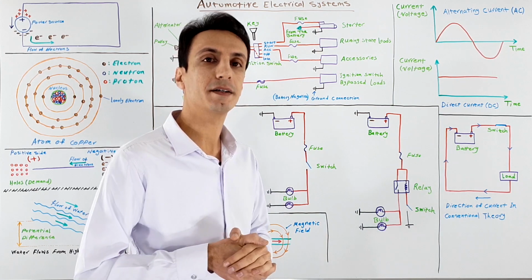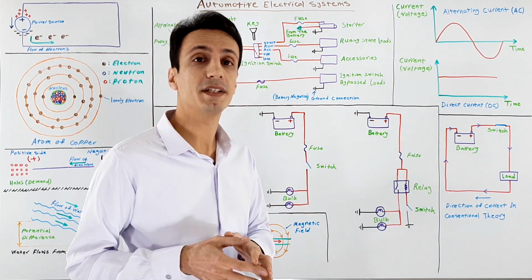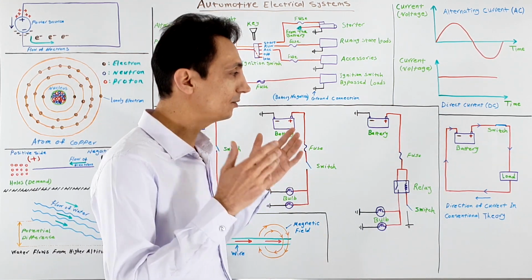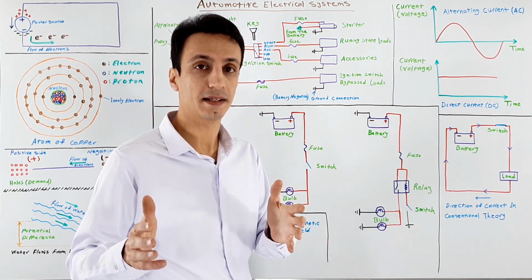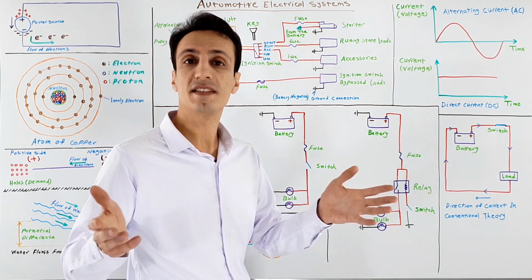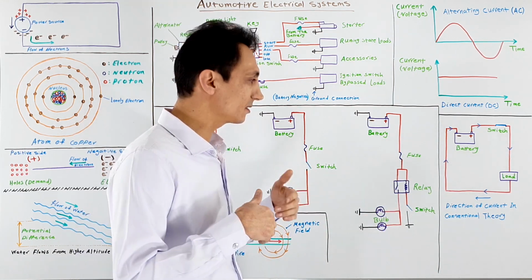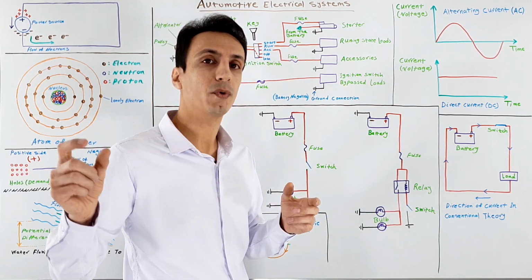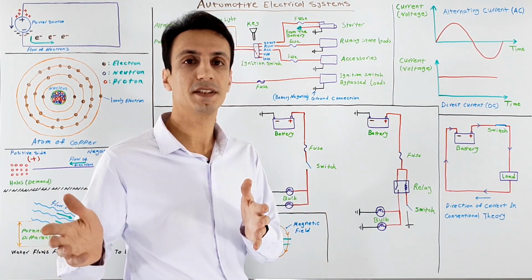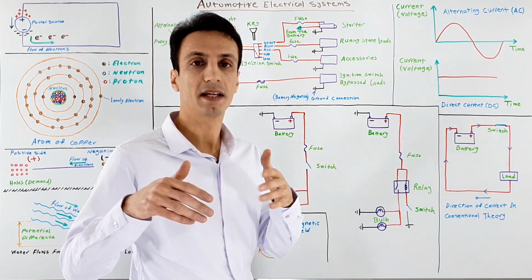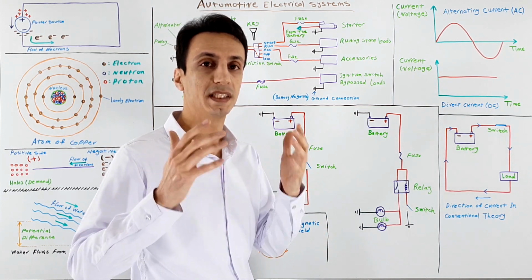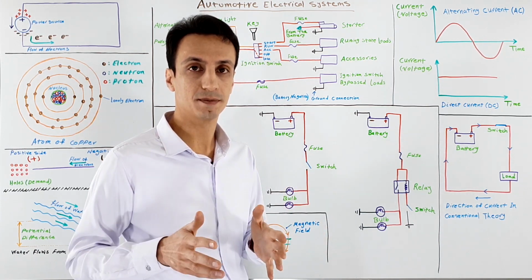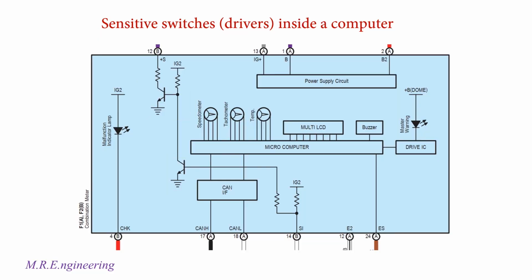Components that demand high currents require larger diameter wires in their circuits, but you cannot use these high current wires in a circuit that the switch is controlling in series. The reason is very simple. It's because the cost of routing these larger diameter wires to the switch and then to the consumers increases, and also sparks and arcing that these high currents make when the switch opens and closes will damage the contact points of that switch. And remember that many of these switches are located inside the sensitive ECUs.